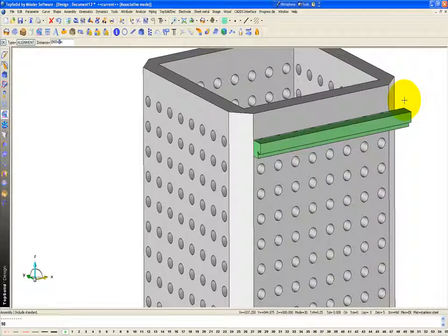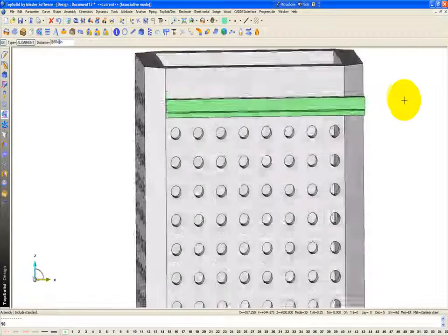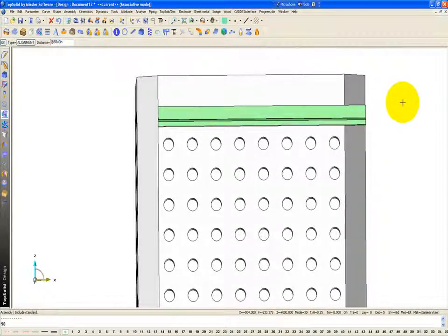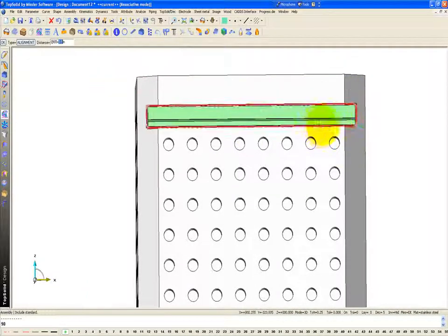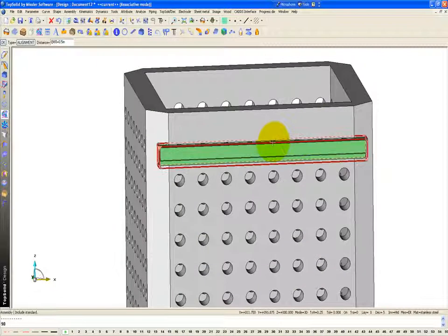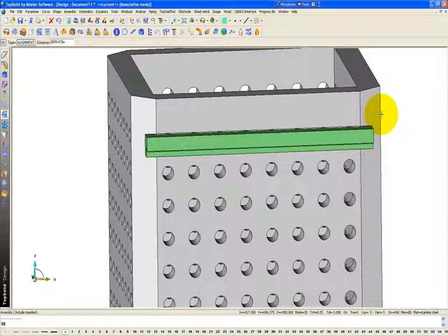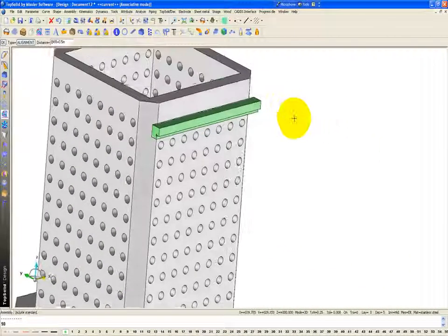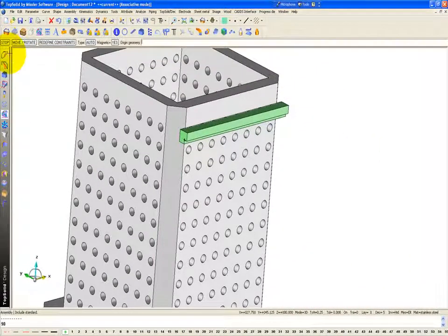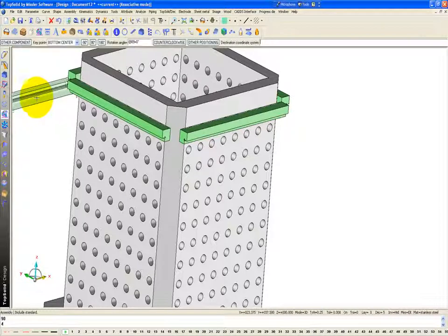And by selecting that face, that applies an alignment, and you can see it's off to one side. I'm going to type maybe 0.5 to get it centered. And so now this top face here is tangent to one of my drillings, and our fixture block is up where we need it to be. Now I'm going to say OK and stop, and here I am going to do a propagation because I'm going to have 4 of them in total. So I'm going to say that I want circular, Z positive, 360, total of 4.